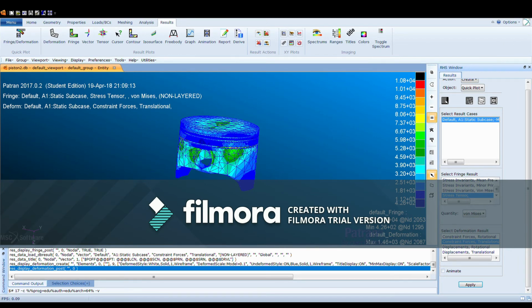A correction had to be made to the previous meshing technique due to lack of the full program and only having the student edition. We had to reduce the mesh components, so we went from a TET 10 mesh to a TET 4 mesh.